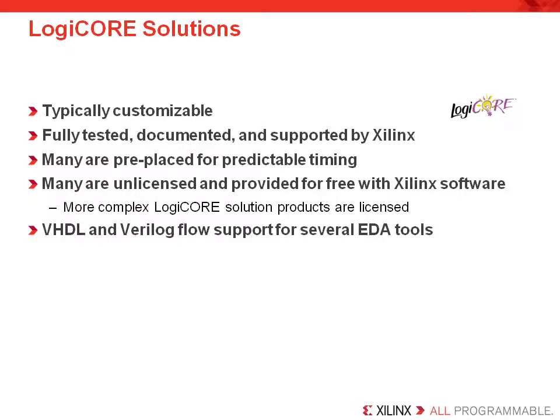Logic core solutions are typically customizable cores. They are fully tested, documented, and supported by Xilinx. Many of them are pre-placed for predictable timing. Many of them are unlicensed and provided for free with Xilinx software, but more complex logic core solutions are licensed. The logic core also supports the VHDL and Verilog flow to support several EDA tools.